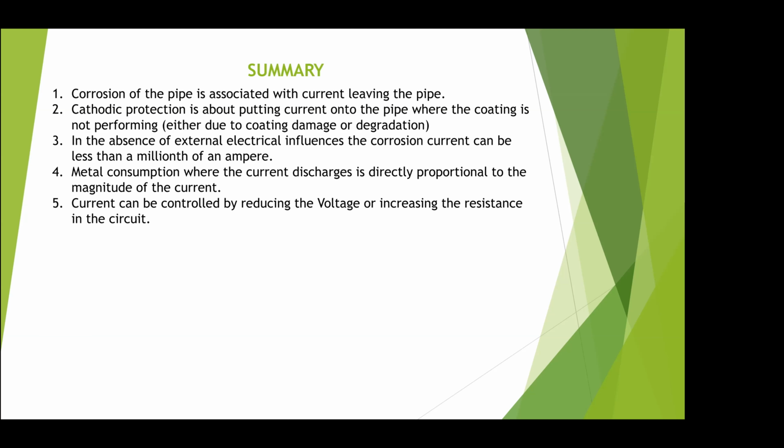And what's happened now is that, in the old days rather, I should say, when the coating failed, it fell off in big chunks. So the current density was quite low because your corrosion was spread over a big area, and therefore you got away with it. But these days, the coatings are so good that you just get a small nick, say 1 centimeter square. All of your corrosion takes place there. All of your 9.1 kilos per amp per year takes place in this 1 centimeter square. And that's why these stray currents are such a worry, because it can be like a hot knife going through butter.